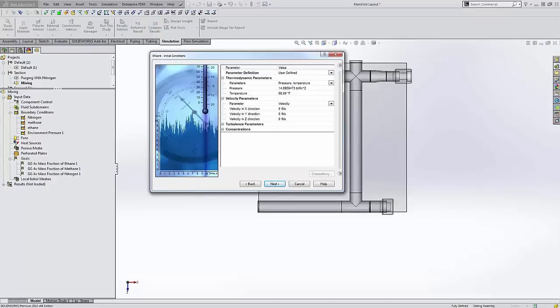Now this next step is something that we typically do not make any settings for in an internal flow like this one, but here we do have to make a setting, and that is in the concentrations area. Because we picked those 3 fluids all being the default, it automatically splits the initial volume into 1/3 of each of those gases. Well, in our case, that's not quite the way the system is.